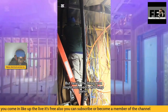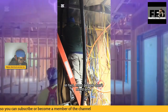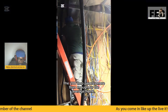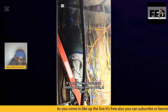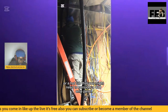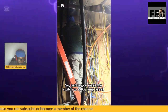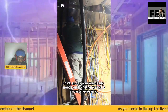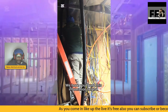The reason for the sheet of plywood is simply because there's going to be mildew inside of the electrical room. There's going to be moisture, and there shouldn't be any moisture getting into the actual electrical panel when you perform your electrical installation. And that is part of a code compliance rule also.